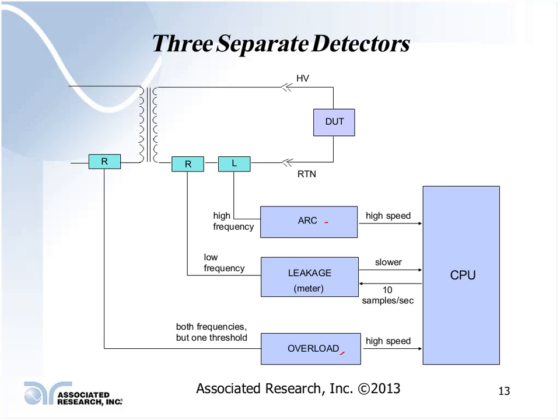If you have the leakage detector, both the high and the low limits, that's a slower detector. It only samples every 100 milliseconds. It looks at low frequency stuff, DC, 50, 60 hertz type scenario, and this will signal either a high limit failure or a low limit failure. Some of the instruments, if you have an overload immediately upon applying your test voltage, will display a short.